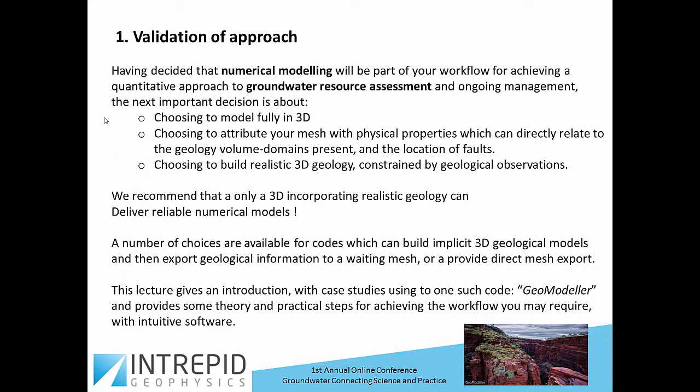Validation of the approach is an important step. It means that you've decided that numerical modeling will be part of your workflow to achieve a quantitative approach to groundwater resource assessment and ongoing management. The next important decision then is about choosing to model fully in 3D, choosing to attribute your mesh with physical properties which can directly relate to 3D geology volume domains present, and the location of faults in your field area.